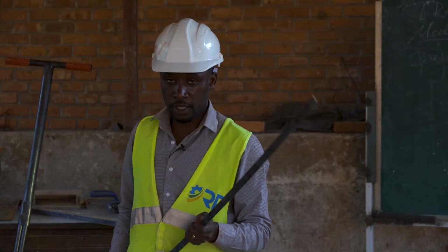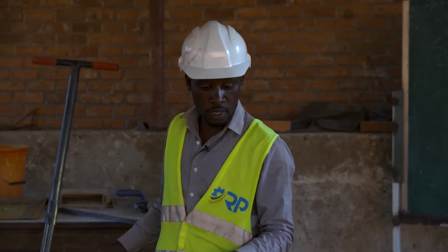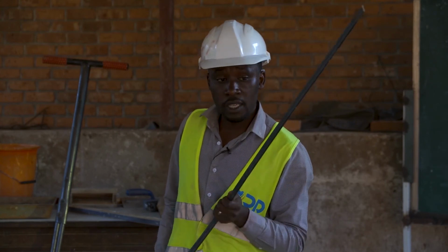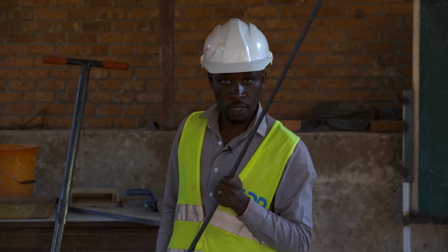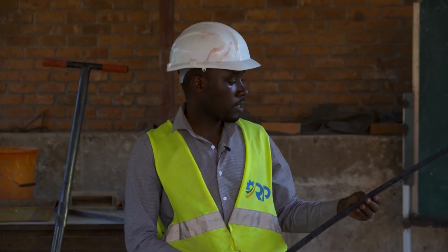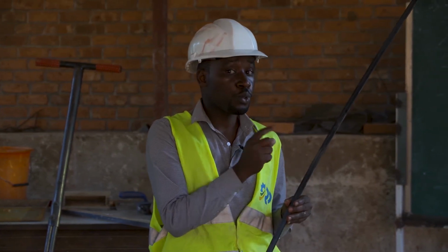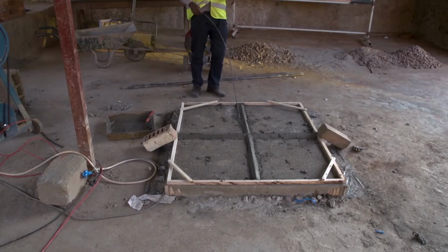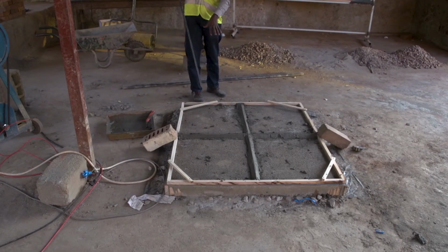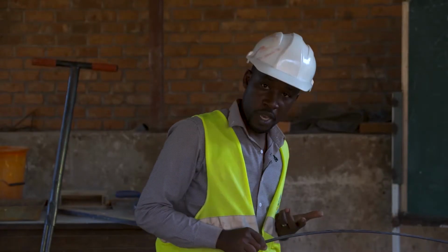This strip divider that we have used when dividing this panel is what determines the total thickness of terrazzo flooring. The strip divider has a thickness of 1.5 millimeter and a depth or width of 2 centimeter. That is why we have to pour the terrazzo flooring material to a depth of 2 centimeter.